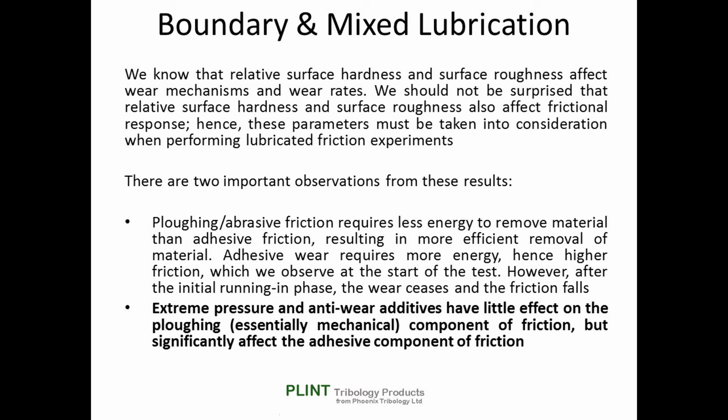There are 2 further observations that can be made from these experiments. Ploughing, or abrasive friction, requires less energy to remove material than adhesive friction, resulting in more efficient removal of material. Adhesive wear requires more energy, hence higher friction, which we observe at the start of the test. However, after the initial running in phase, the wear ceases and the friction falls.